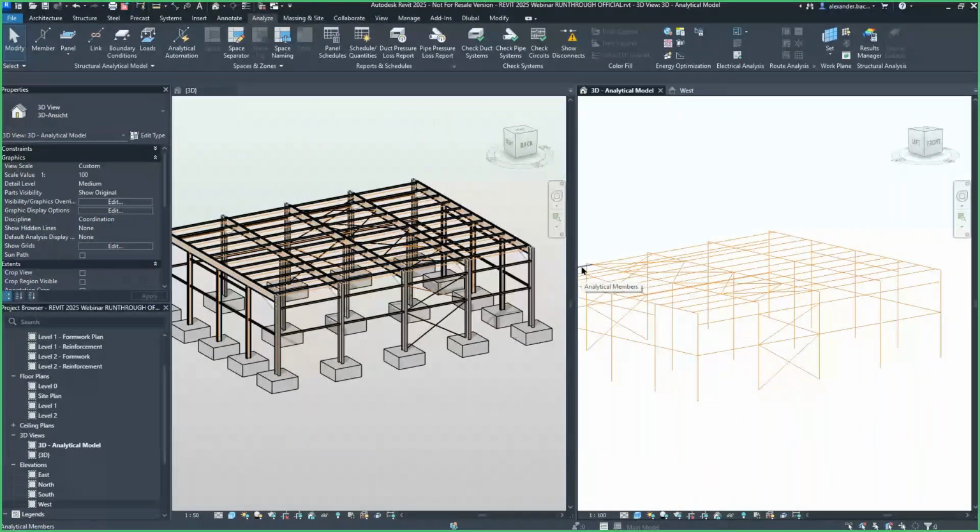So if you wanted to have your Revit model be your all-in-one model, where you're doing your architectural detailing and also running the structural, or creating the structural info, you can do that. Or you can simply just leave it up to the structural engineer and just export the analytical model into RFEM. But totally up to you. So now we'll go over exporting this to RFEM.